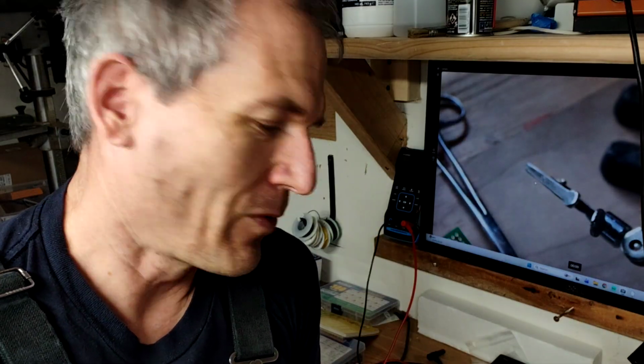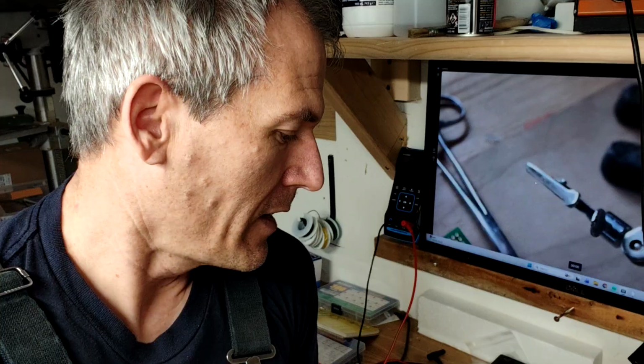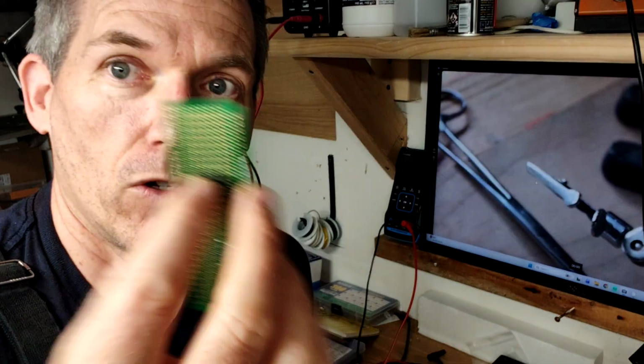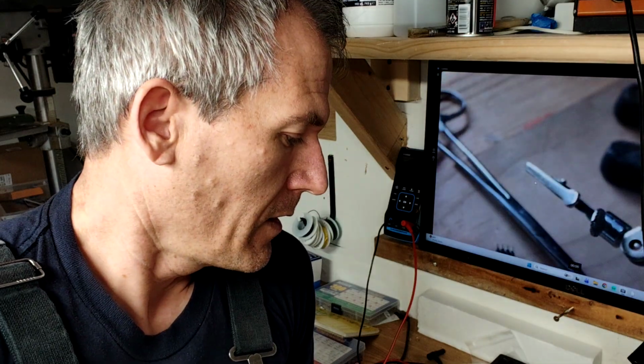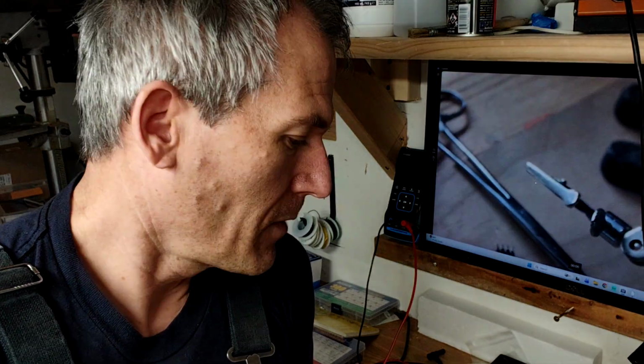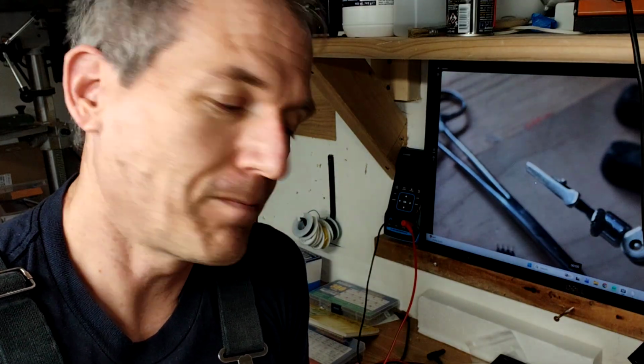I mean, each joint that you have to solder is another piece of work you need to do. If you can get by with 3 legs on a BJT instead of 4 legs on one of these OpAmp packages, so you get 2 on each 8-pin DIP. Just something to think about. Also, more legs means more space on the protoboard, or more space on the PCB in the final design.